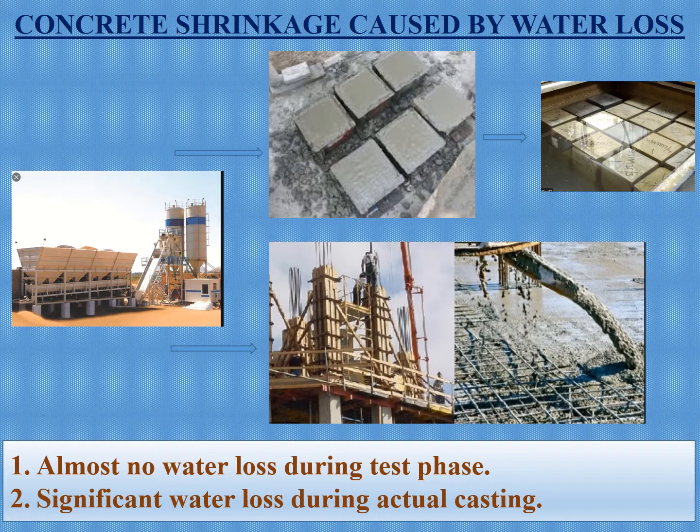Normally in practice, during the actual casting process, in industry we practice the following to avoid this kind of water loss. Wet all contact surfaces before concreting. Avoid casting at noon as much as possible. Cover the completed surfaces to prevent evaporation.